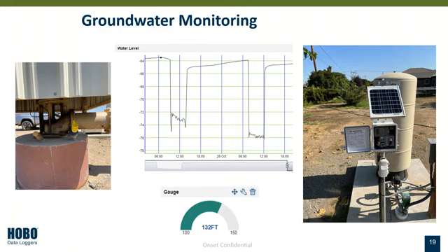One other thing that you're able to see is what's your drawdown like, right? If you're doing real time, you're going to be able to see how much the water draws down when you turn on your pump. So this is another great factor to be able to know. You're able to know if your well is safe, if you have enough water, right? If your water is getting so low and you know where your pump is set at, you're able to indicate, okay, do I need to lengthen my well?